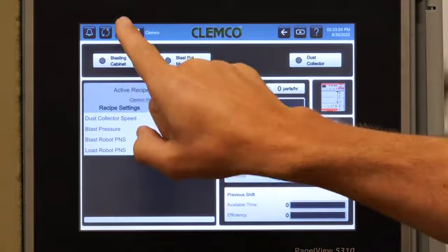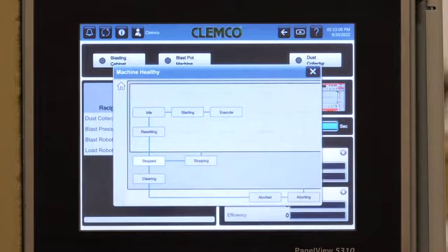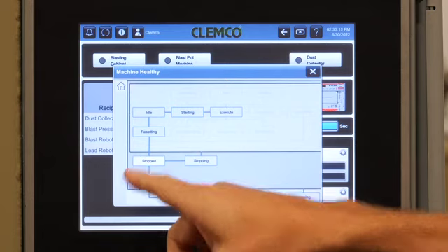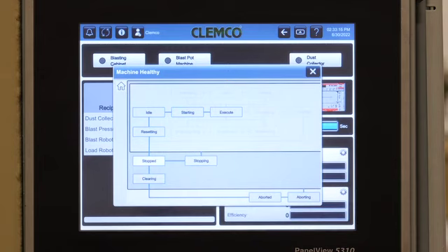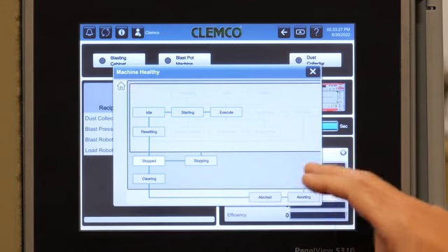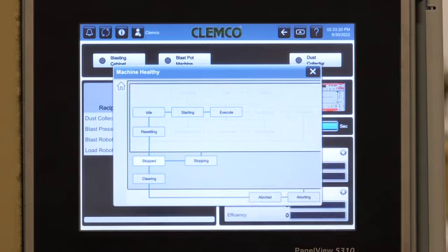The rest of what's on top here, this information button pulls up the state machine of the entire piece of equipment, and it tells you what state it's in. For instance, right now it's stopped. It could be rebooting, aborting, canceling, resetting, starting, executing. Those are all states of the machine, what it's doing. And then down here you'll see later, that's what step it's in, what step it's executing while it's in the executing state.